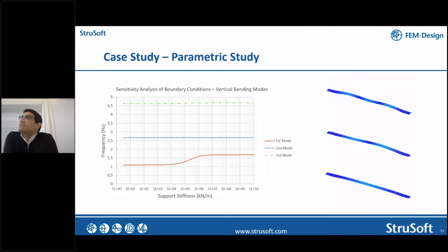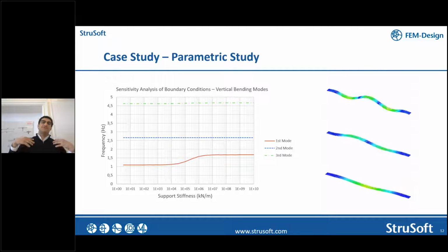So why is this important? Because you are varying the natural frequency of your system. This is telling you that your system is bounded to be between those two natural frequencies for the first mode of operation, the lower and upper bound, because we have identified which degree of freedom had the influence for this particular system.